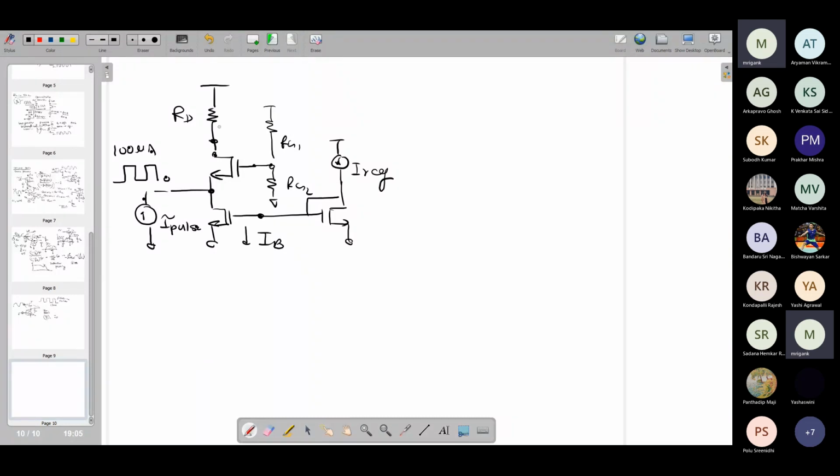And then you also need an input impedance. So here I am putting an input capacitance of 0.5 picofarad. This is 0.5 picofarad input capacitance. And the input resistance of this one is, say, what? Suppose 2 kilo. I'm trying to make it a little challenging. So 2 kilo, and this is 0.5 picofarad. And this is the source.